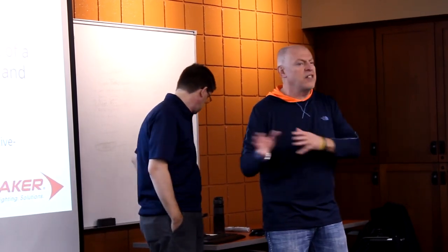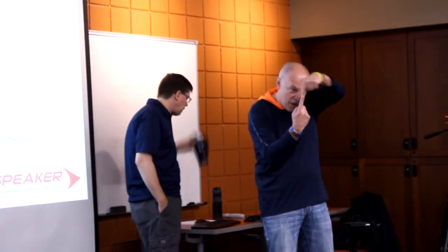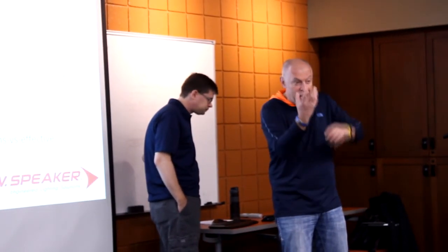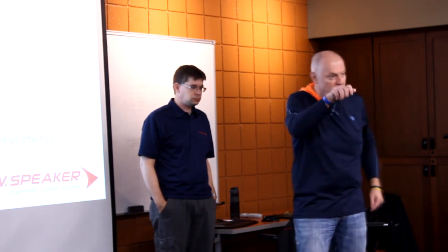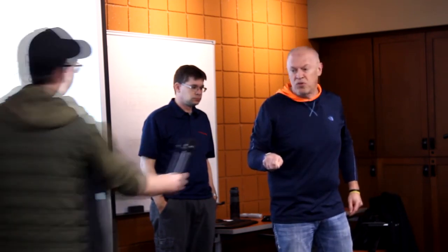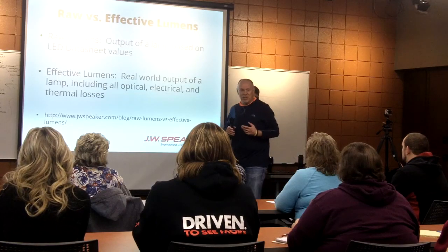So basically, a bulb, for example, let's say an H11, is around 1200 lumens, which means that filament radiates all the way around, like an apple. That's the radiation, really radiating all the way around. That's the raw lumen, and it has around 1200 lumens. When you take that bulb and put it in the reflector, most people know what a reflector is, you're getting really 30% efficiency.